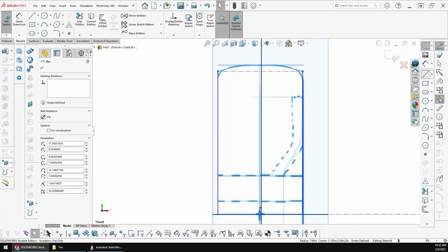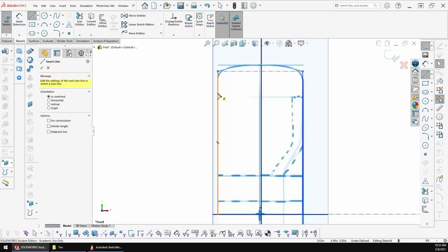So we talked about whether or not we would push our rear wheel cutout as a separate feature or within the sketch. The nice thing about the more you can do in a sketch is the fewer commands you have to do later, and you can adjust things all in one area. So with that said, let's toss this wheel cutout into our profile.